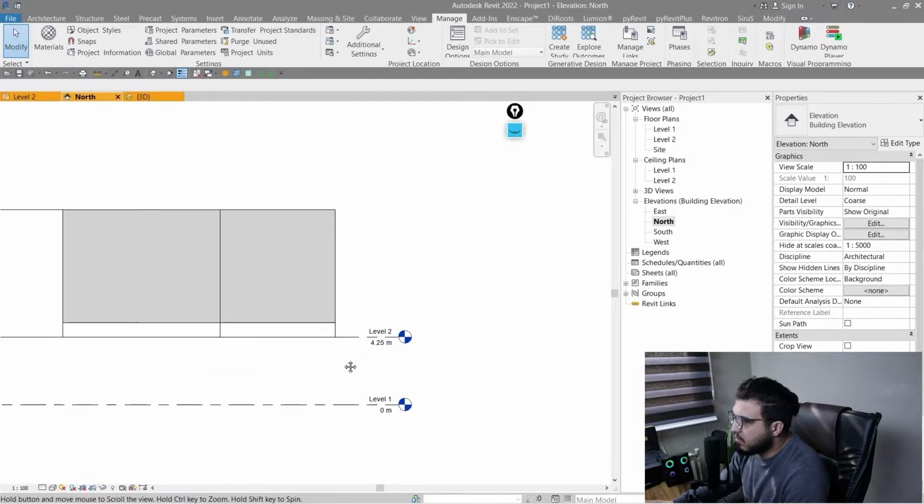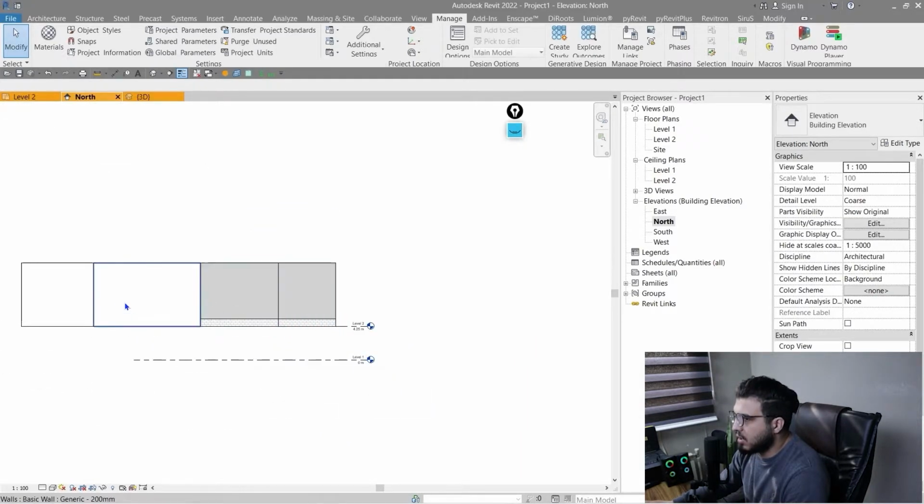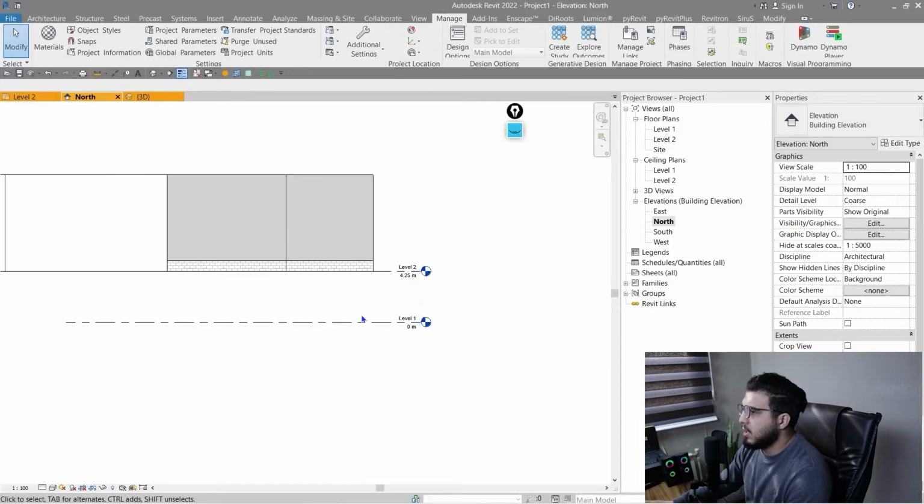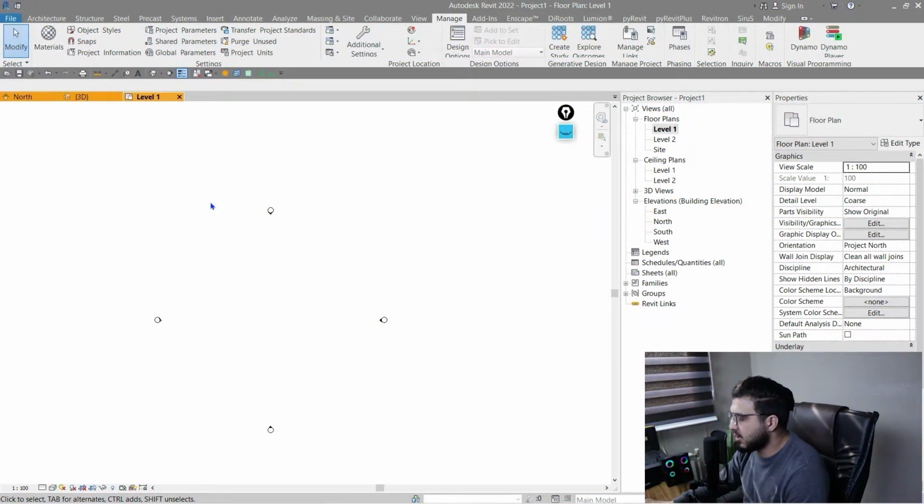And the next thing that we want to know after assigning and setting the unit, now we can create some new elements in Revit. Before doing anything in Revit, you need to create levels in Revit. In any building, we have levels.